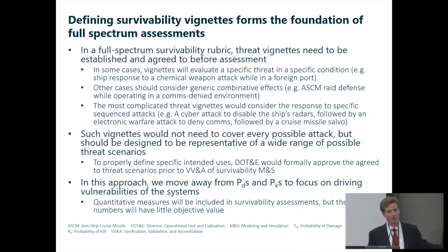And I've been doing that for a long time under LFT&E. A lot of the stuff that we come out with, we don't want to focus on the PK because in a lot of cases the PK is low fidelity anyway. But we do want to say, hey, this system is critically vulnerable because there is a single point of failure here, and it's right in the center of the ship, and that is right in the crosshairs of most of the weapons. Please move that to somewhere else on the ship or build in some kind of redundancy that gives you the ability to defeat that.